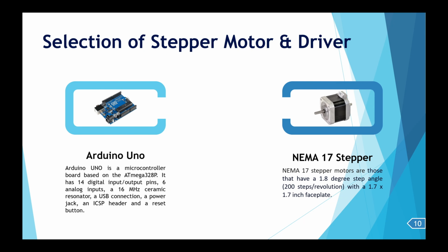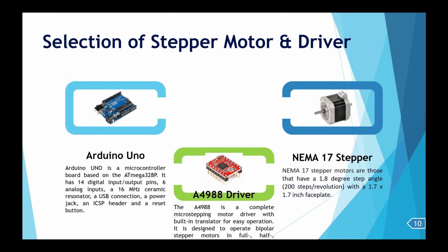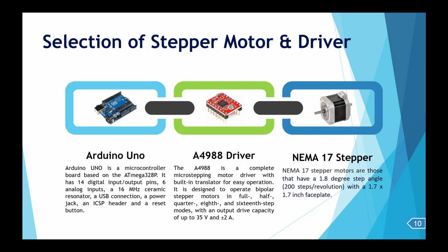Now Arduino alone is not sufficient to feed the pulses to a stepper motor. So to handshake between the Arduino as well as the stepper motor, we need a stepper motor driver. However, there are different drivers available to control different bipolar stepper motors. We are taking the cheapest driver, which is called A4988 driver.